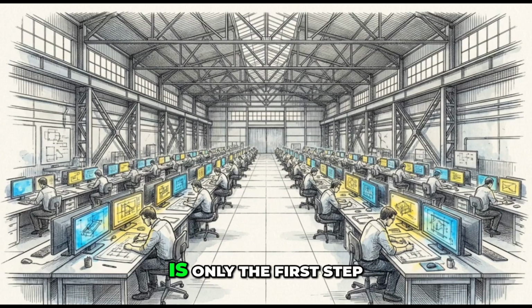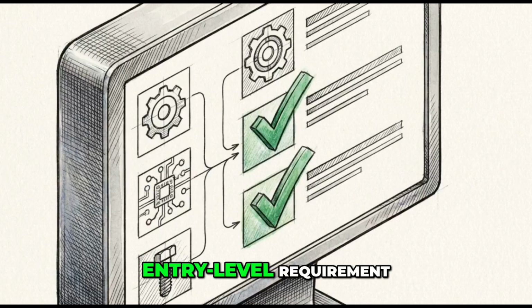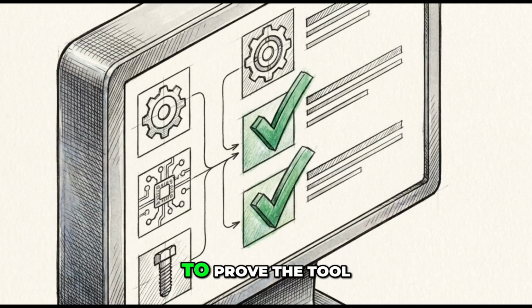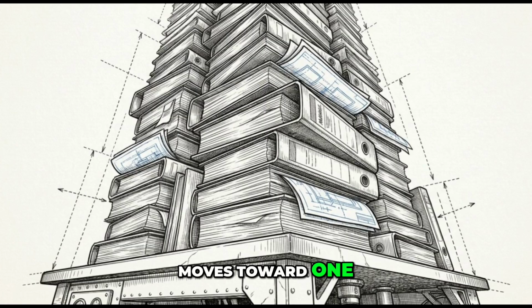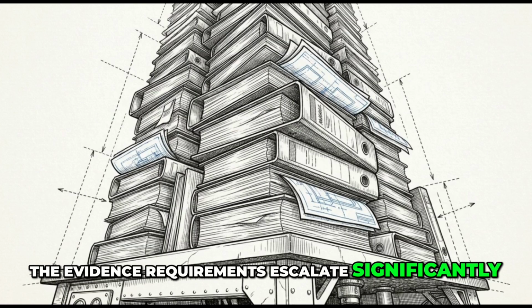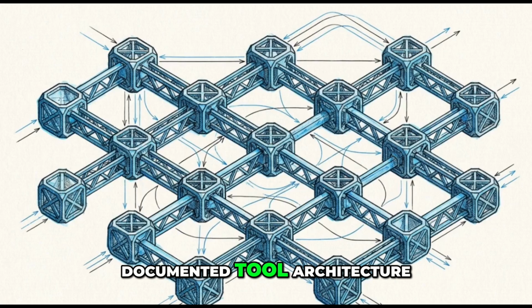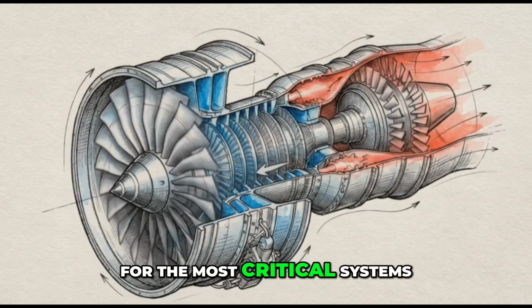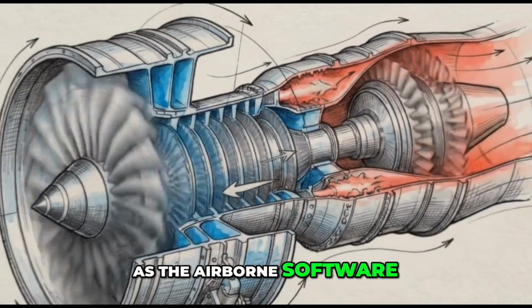Assigning a TQL number is only the first step. The real complexity lies in what these ratings demand from the engineering team. TQL5 is the entry-level requirement. It requires basic tool requirements and operational verification to prove the tool works in its target environment. As the TQL number moves toward 1, the evidence requirements escalate significantly. Lower TQL numbers add the need for low-level tool requirements, documented tool architecture, and structural coverage analysis of the tool's own source code. For the most critical systems, the automation tool must be verified with the same level of rigor as the airborne software it generates.